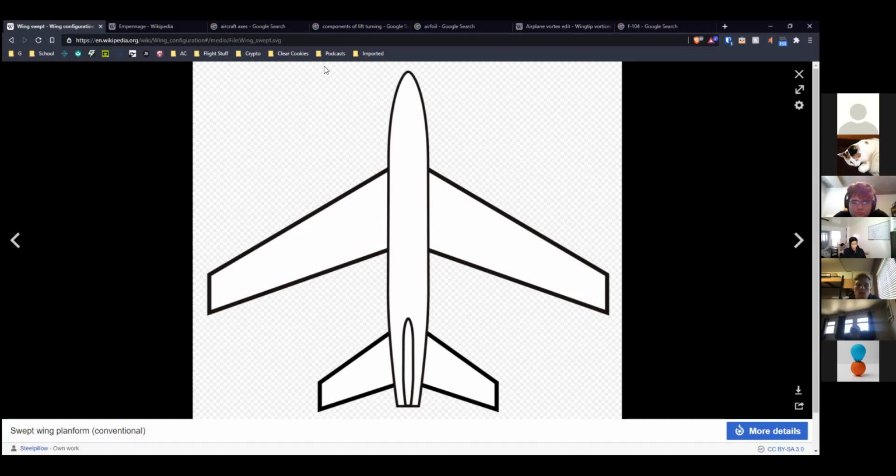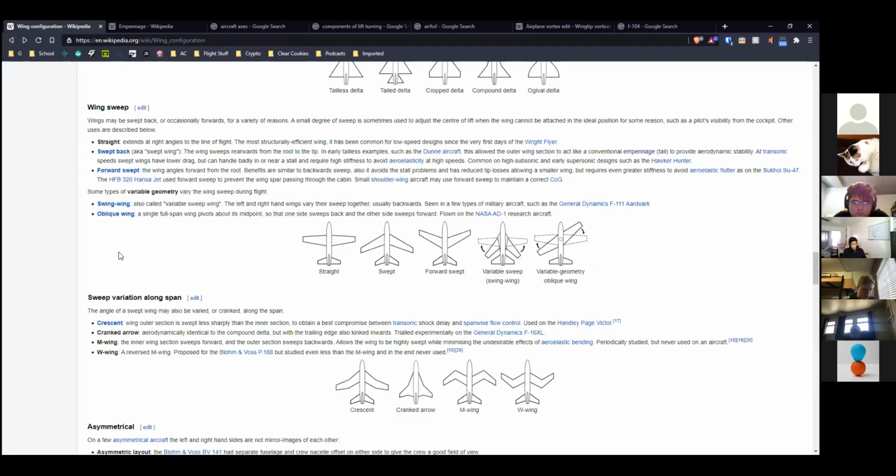It's just that if you look at it from the perspective of an airfoil section, in the chord direction, then it's seeing the air as coming from an angle. And so then you can treat the components of the movement of the air as in the direction of the chord and perpendicular to that direction. But our planes don't exceed 0.15 Mach or whatever. So we very rarely have to worry about that.